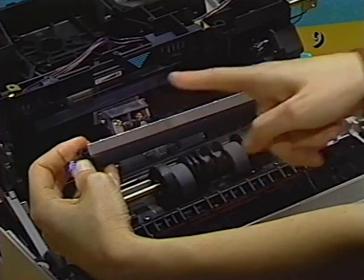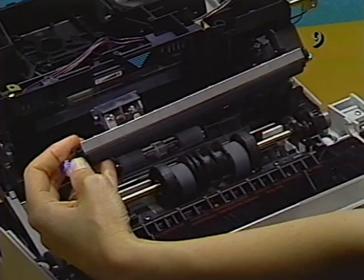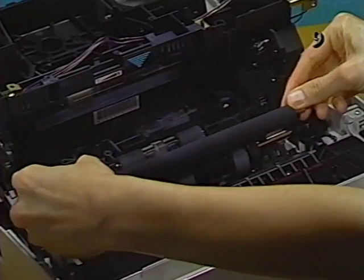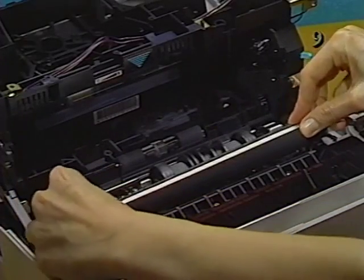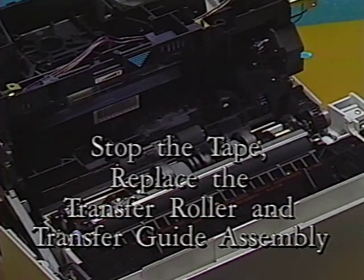Make sure the 2 black plastic arms fit over the pickup roller shaft and the transfer guide grounding bracket is properly aligned with the pickup roller shaft. Finally, press down on the transfer guide assembly until each end of the roller shaft snaps into place. Stop the tape and replace the transfer roller and transfer guide assembly.